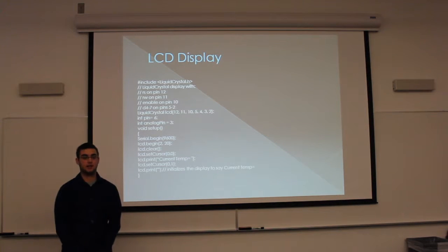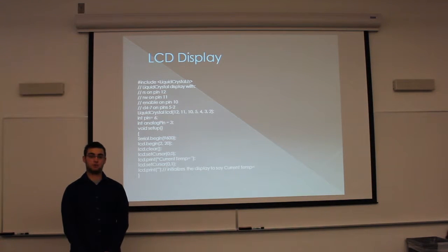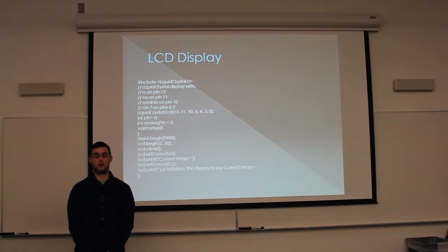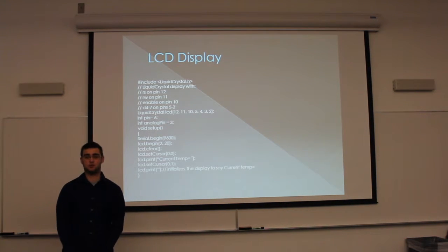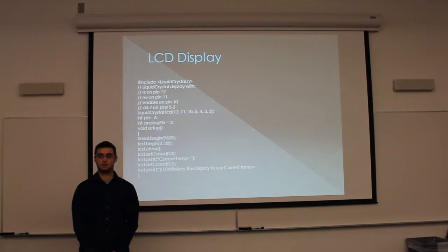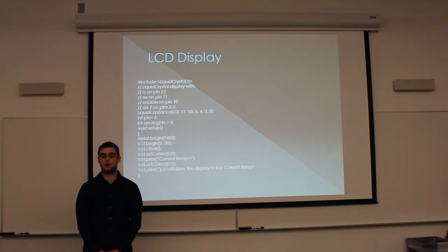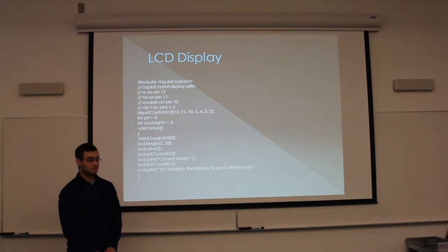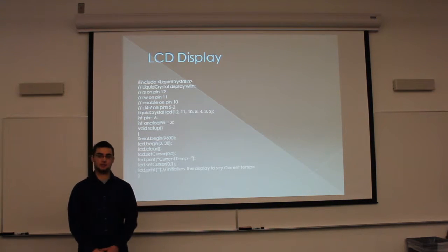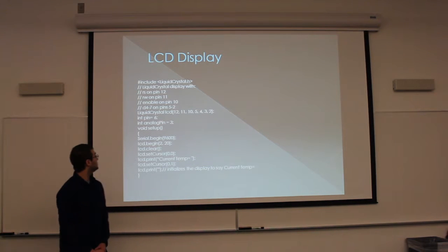The one that we did in class was a voltage reader. We set up a circuit with a voltage divider, and we had a pin connected to the Arduino that would measure the voltage. For this one I actually have it hooked up to the temperature sensor to combine them. So that's what the LCD is, and this is some of the sample code that's used.